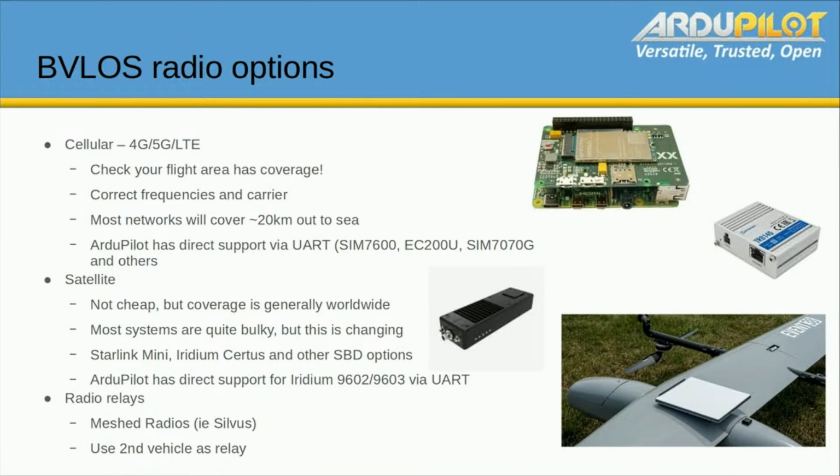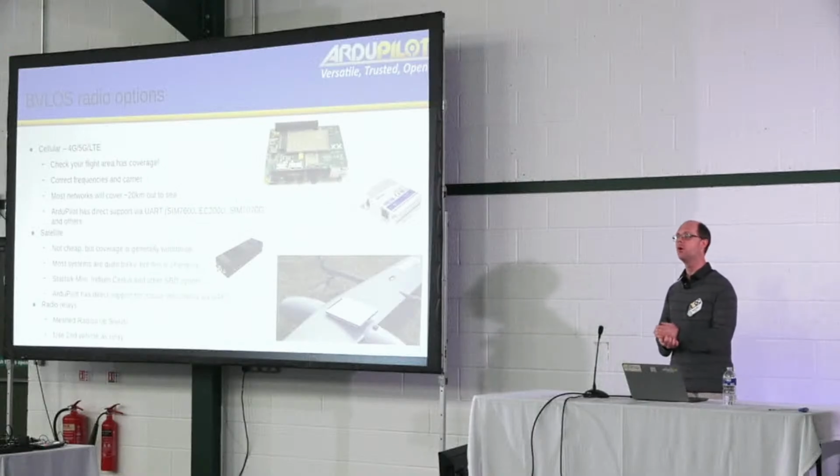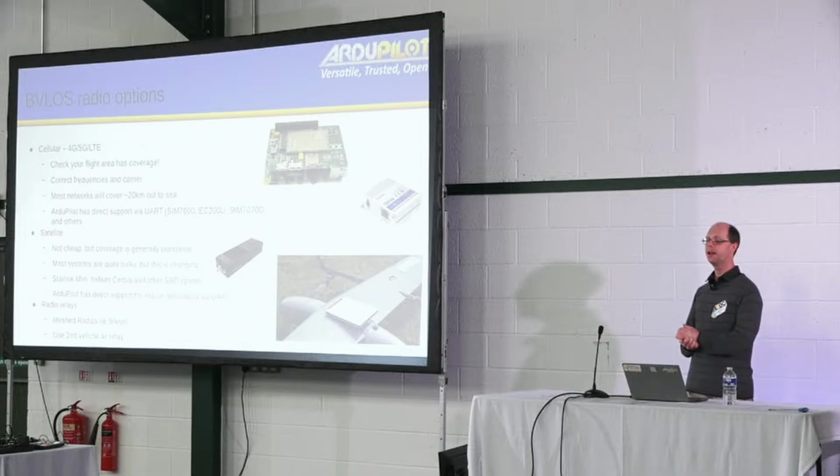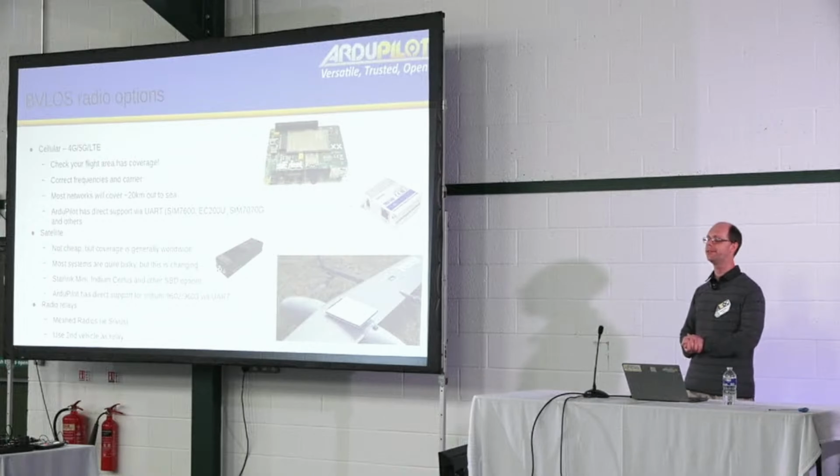It is a lot cheaper than it used to be. 10 years ago, you were talking about dollars per megabyte sorts of fees, which did make it impractical for UAS. It is getting better, but you're still looking at satellite systems being, on average, an order of magnitude more expensive than your cellular systems.